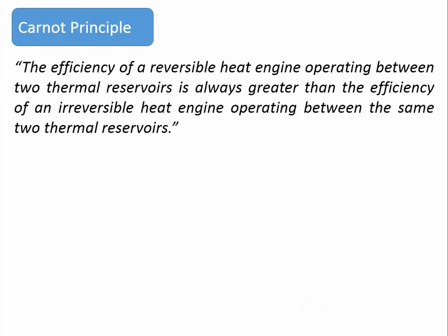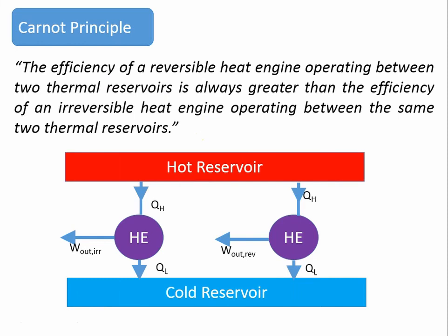Carnot principle is a corollary of the second law of thermodynamics. It says the efficiency of a reversible heat engine operating between two thermal reservoirs is always greater than the efficiency of an irreversible heat engine operating between the same two thermal reservoirs. We can examine this further from this schematic diagram.